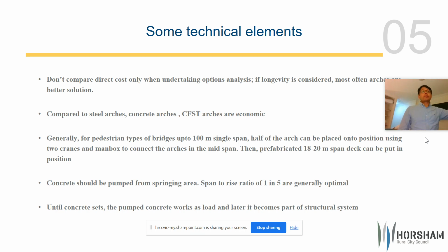But in the service stage, the structure is different, so you have to have that analysis. When you are lifting the arches, you have to make sure that there is no local buckling in the members and braces and things like that. So they all have to be considered. As I said, there are good codes in China for that, but if you apply simple general mechanics, then it should work as well.